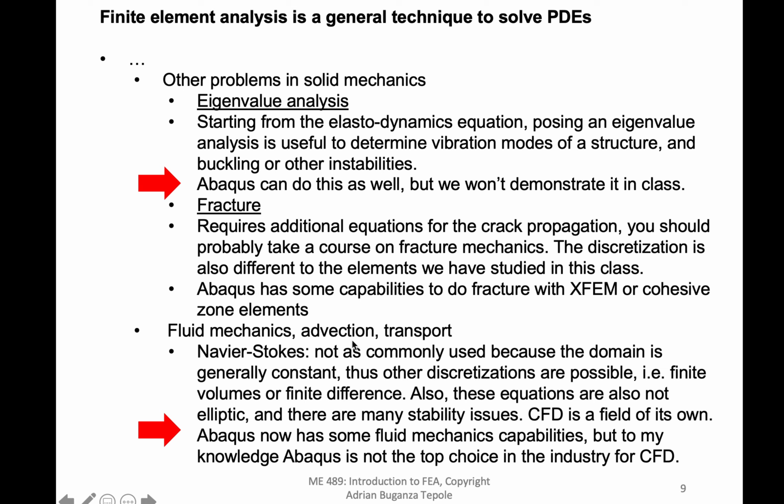Fluid mechanics, advection and transport, for example, Navier-Stokes. I don't think it's as commonly used in Abaqus, and actually the finite element method may not be the first option. This is because usually you have a constant volume, so you can use other types of discretization, such as finite volumes or finite difference. So the finite element method is not always used for Navier-Stokes, but it can be used.